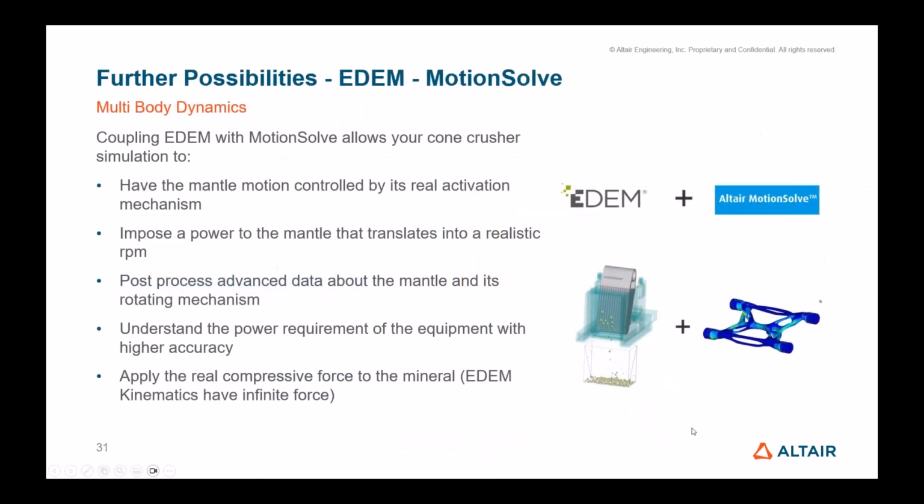And the last topic I wanted to touch on today, which is about further possibilities and how to build a more advanced system with your either cone crusher or whatever equipment it is that you are simulating breakage with. And it's with the addition of multi-body dynamics, which in the case of the Altair ecosystem, we're talking about Altair MotionSolve, which can be easily coupled with EDEM, which means that the MotionSolve, the multi-body dynamics tool, will control what's happening with the equipment, and EDEM will only control what's happening with the particles. And these two solvers will have a dialogue and will pass information to each other, but each one of them will take care only of their separate matters.